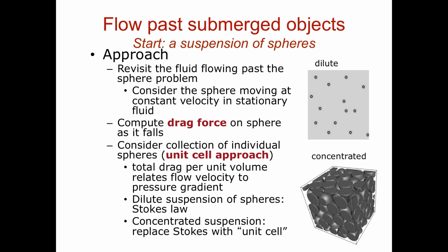Right? And we will stretch our solution to actually somehow fit into this definition and basically depend on the porosity of this sphere pack. It's going to be an interesting exercise, and this is the so-called unit cell approach. Okay? So I will ultimately fit a whole bunch of spheres together, and I will look at the balance of forces again and the total drag per unit volume of these spheres, and that will essentially give me a formula for permeability of this medium. Okay.